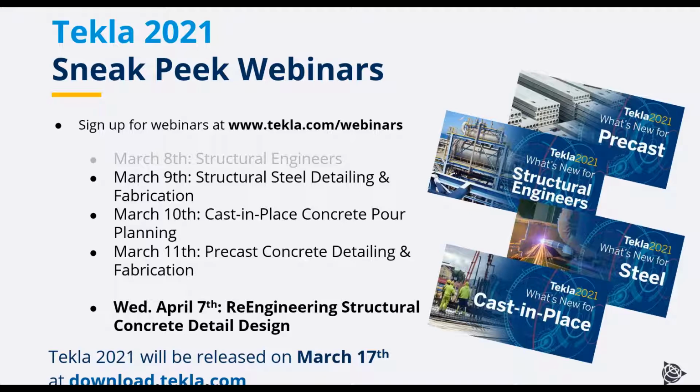That's new for this year, is now you can bring a Revit file direct into Tekla in the same way you would an IFC. So on those projects where perhaps the team aren't comfortable or not familiar with using OpenBIM and ISO standard IFC files, they can certainly send you a Revit file, 2021 Revit, and we can import that direct into Tekla.